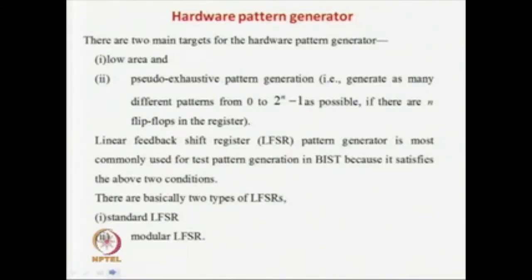So, you replace the chip and only then will your circuit start operating, otherwise you cannot operate your system with a faulty chip. That is another advantage of BIST: with one or two faulty chips your system will not start operating, so that in the middle of some operation you do not get a malfunction and lose your data and so forth. It will not allow your system to boot up, saying that there is a problem here, you better replace the chip and then start the operation. So, that was about the basic BIST architecture and its requirements.